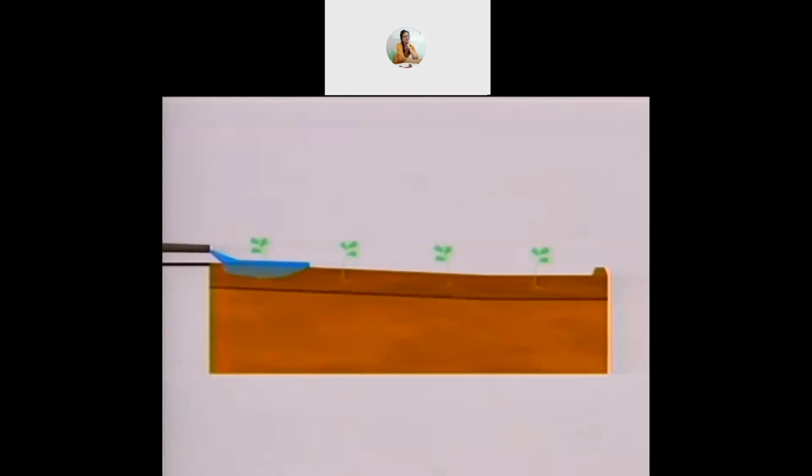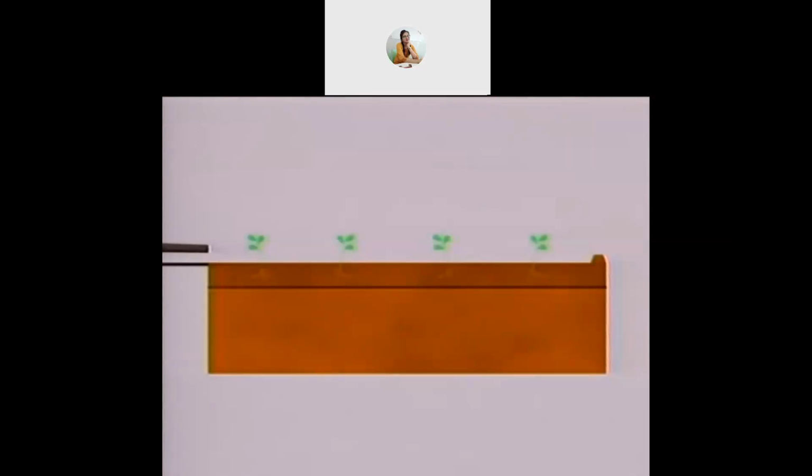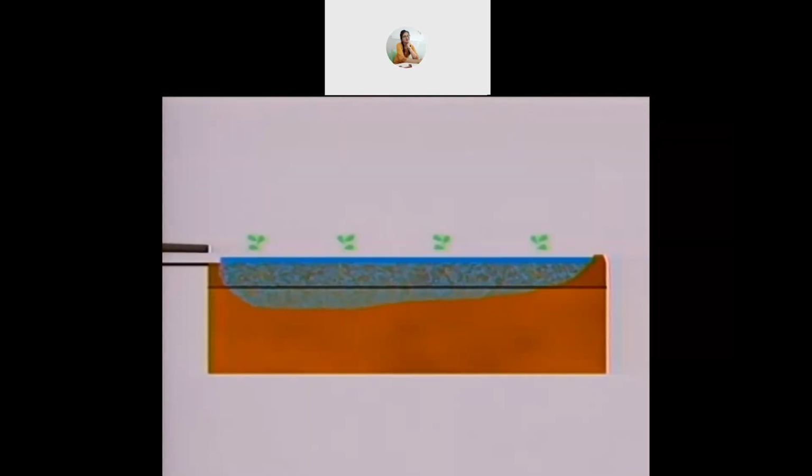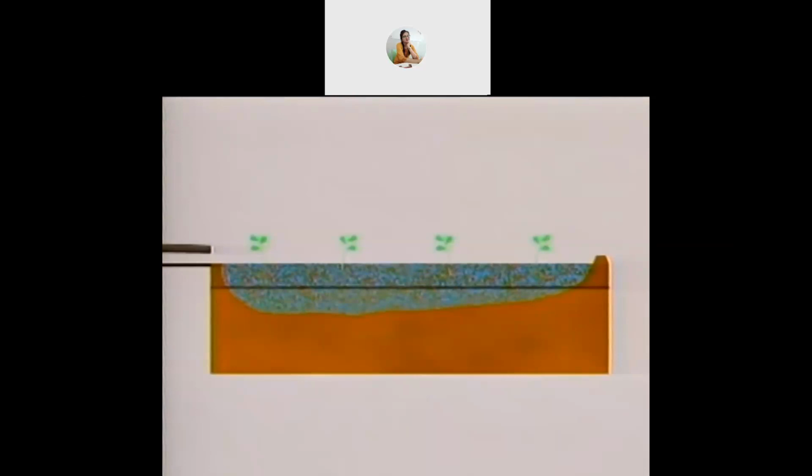Number 3 is sprinkler irrigation. Its advantages are: A. Suitable for all types of field condition. B. Uniform distribution of water with high efficiency. C. Less land loss provides more land area for cultivation. D. Loss of water is minimum. E. Accurate and easy measurement of distributed water. F. Soluble fertilizers, herbicides, and fungicides can be added in water before distributing to the crops.